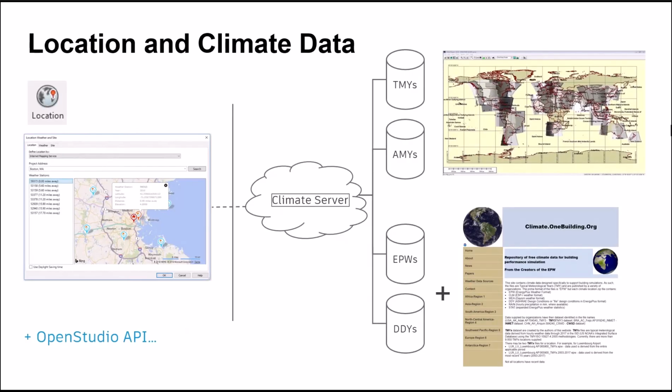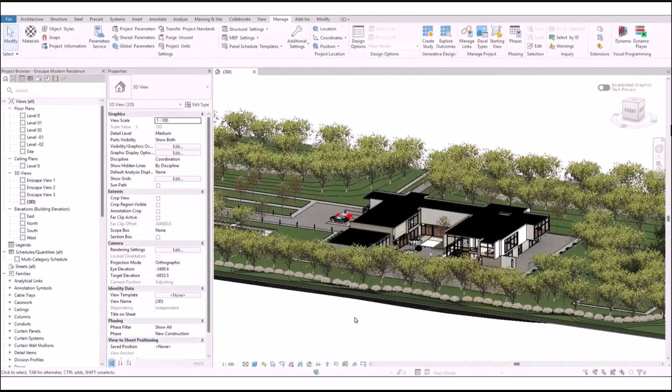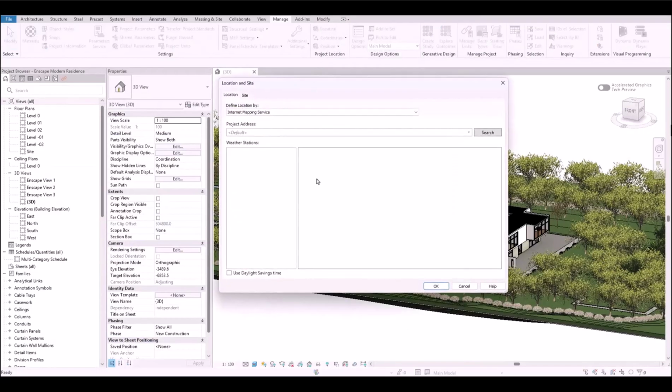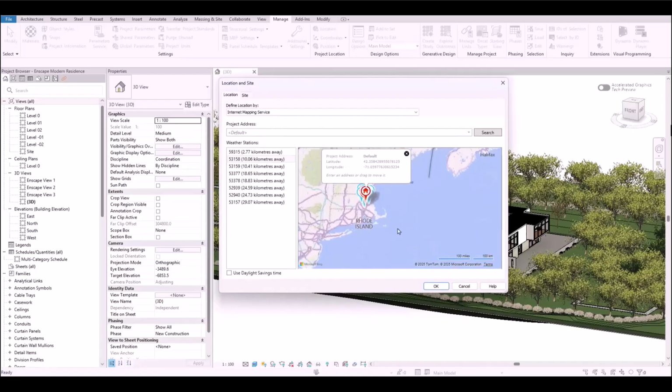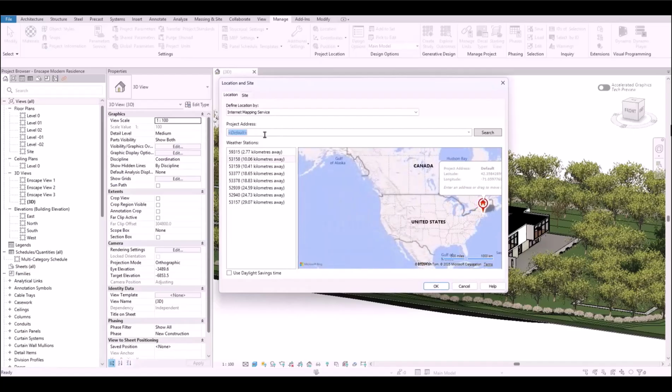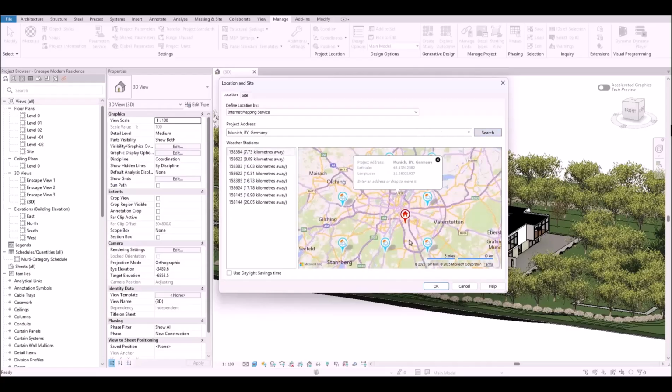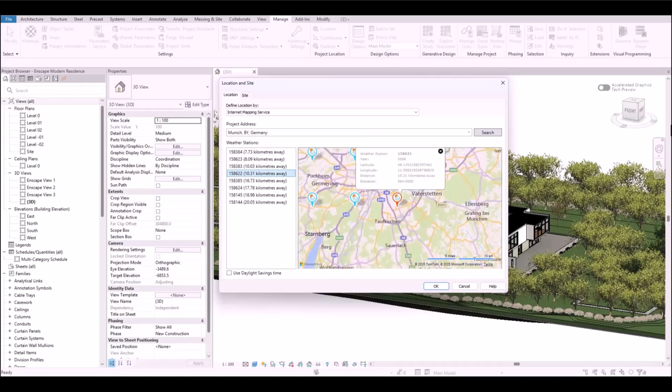This allows Revit and Insight to pull the right weather and climate data from the cloud. These files include hourly temperatures, solar radiation, humidity, and more, all needed for accurate energy simulation. So we should set these, let's say, in the first steps before we create analytical spaces or run any calculations.